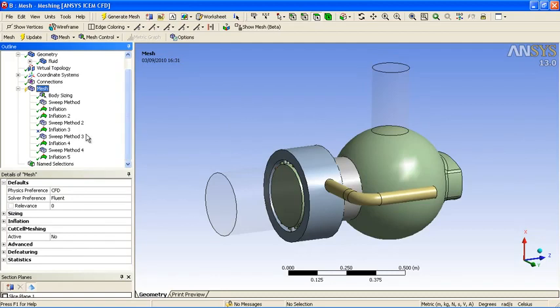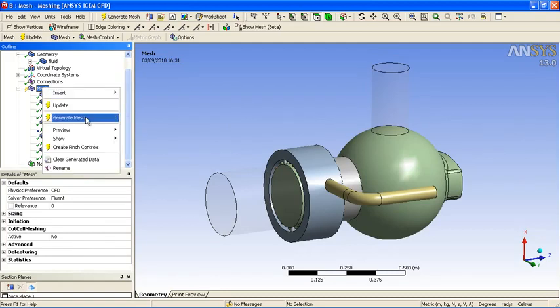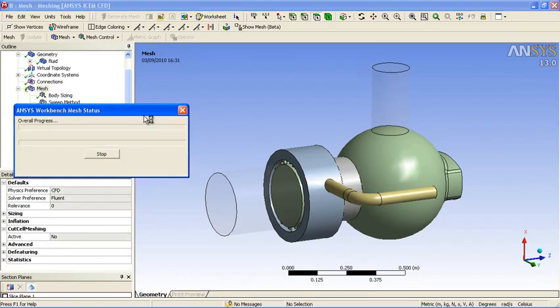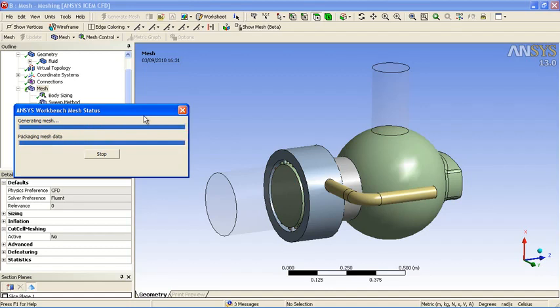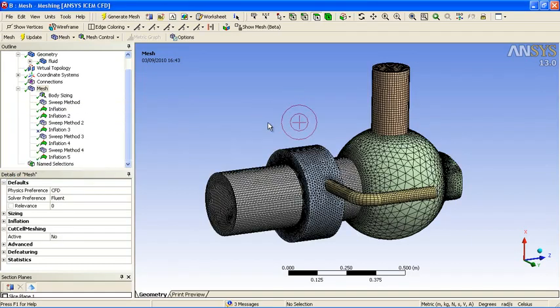So this decomposition may only take a few moments and will allow you to generate a much more efficient mesh. The mesh generation tool will generate tetrahedrals and inflation layers where specified and swept meshes, and will also combine them to make them node consistent. So this will be one continuous mesh with multiple mesh methods all used at the same time. So you can now see the resulting mesh. You can see a large number of hexahedral elements due to the decomposition of the model.